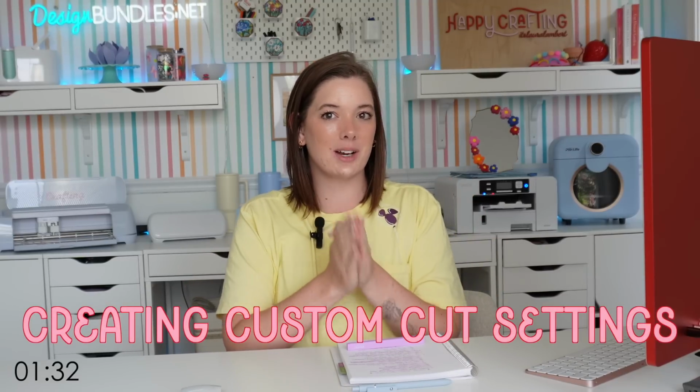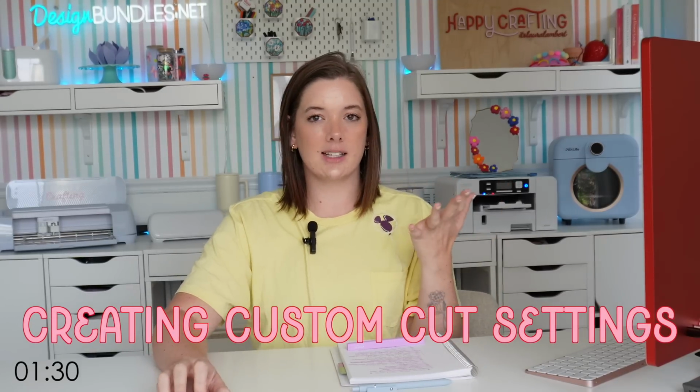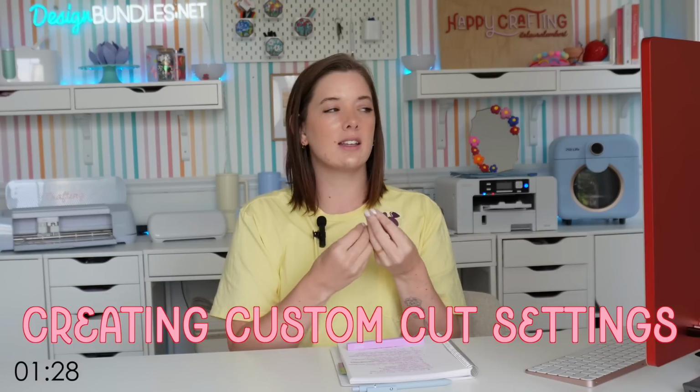Okay, the very last tip I'm gonna show you today is creating custom cut settings. Maybe you like to cut a custom material and you've just realized that it really works the best when you cut it on the medium cardstock setting, but with a little extra pressure, and you don't wanna use the more pressure setting. You just wanna be able to have it in there all the time because you cut this material a lot.